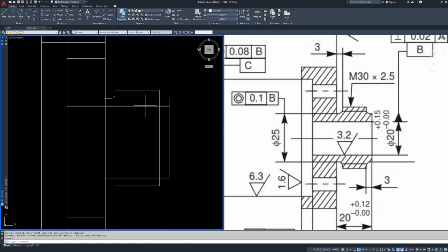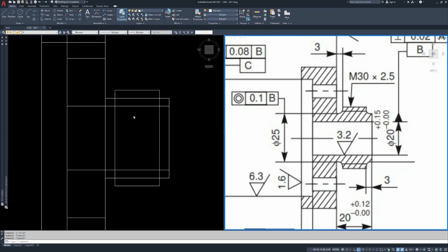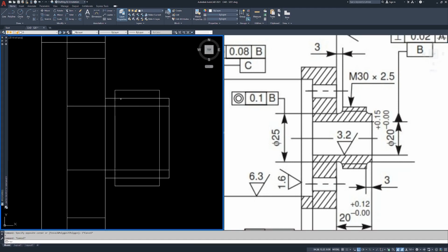So what can we do? We can either mirror this over and then mirror both down, or we can undo. We can use our trim command, trim out this centerpiece. Actually, I need to trim this one too. Do the same thing here. Cut out those centerpieces. Now all 4 of these corners are independent lines, so we have 8 lines total instead of 4.